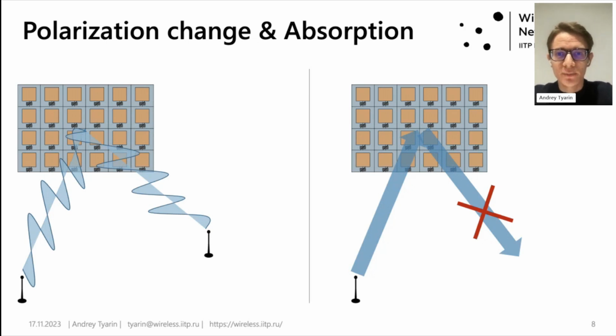To change the polarization of the reflected EM wave, UCs need to have anisotropic properties. For example, it is possible to change polarization for a 45-degree polarized EM wave via RIS operating only with horizontal polarization.